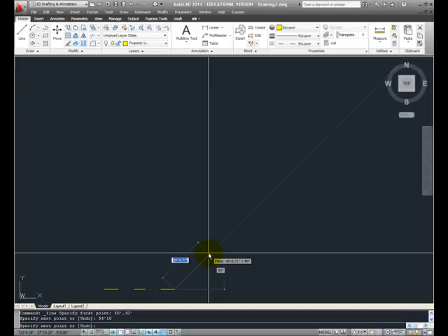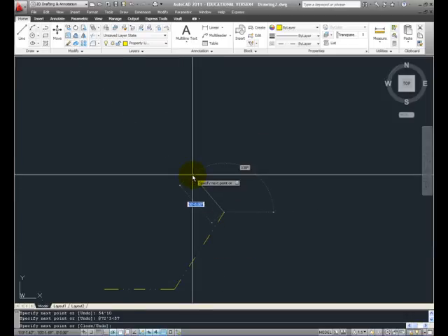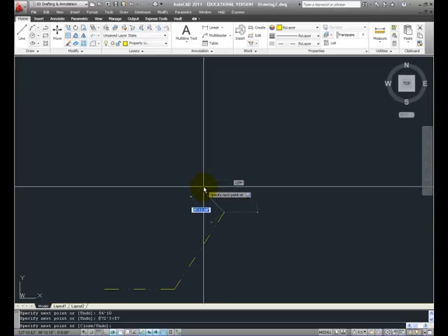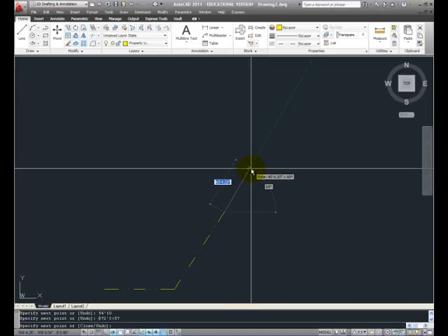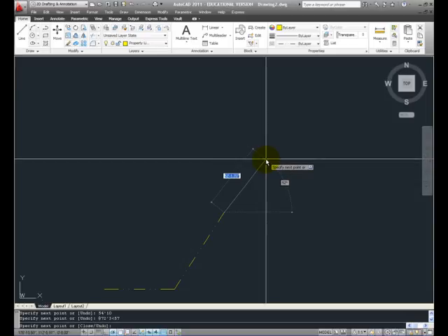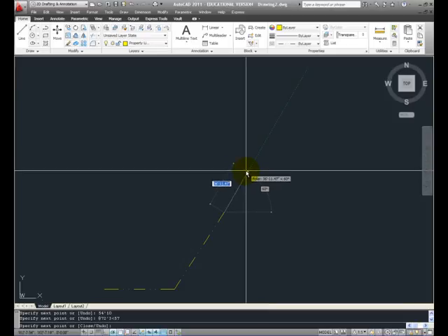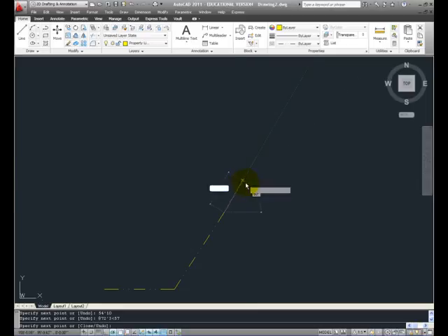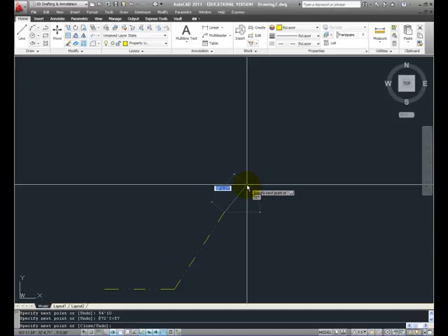The next line is going to be drawn at 72 feet 3 inches and an angle of 57 degrees. That angular measurement was obtained by starting out with 180 degrees, from which I subtracted 123 degrees, and then I added to that the previous angle of 0 to come up with 57 degrees. All other lines in this exercise will be created similarly.